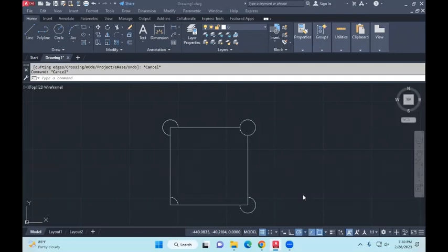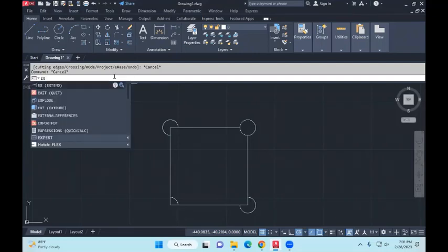So you have already trimmed them, inner, outer. There you go. Now let's carry on from here. Kind of like the opposite of trim is extend. I can't find the symbol for extend in modify, so let's just type it out in the command box. Extend, so EX. Once you start typing, the first one that comes up, the shortcut is EX. So the first one, click on extend.